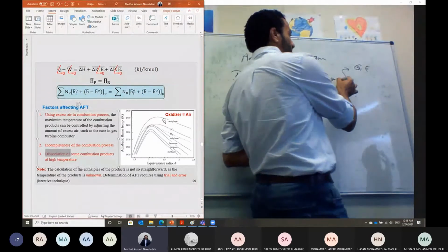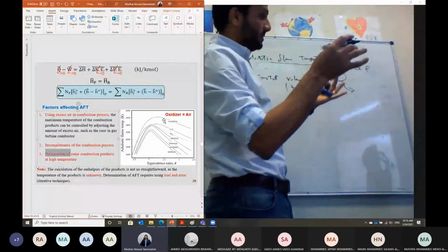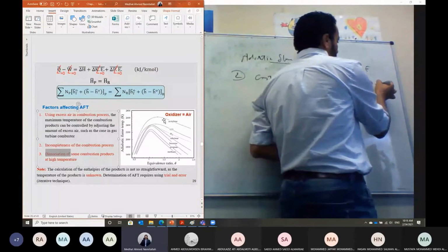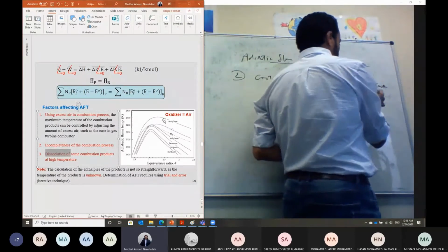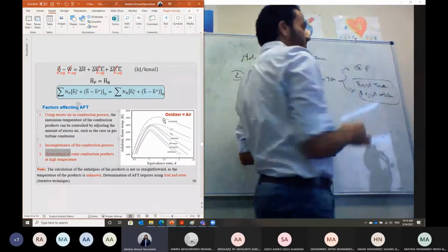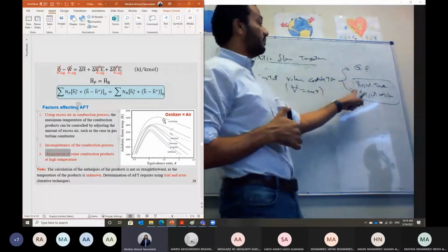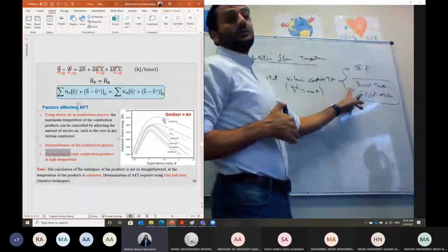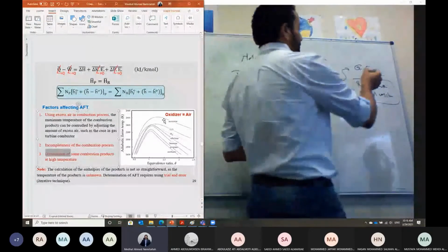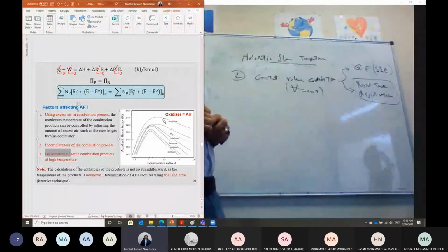And also, guys, if we have an explosion in a fuel tank or something, this is a closed tank. We call it a rigid tank, or a rigid vessel. All of this is a closed system of constant volume. So if I told you I have a rigid tank, rigid volume, closed system of constant volume, or a gasoline or spark ignition engine, that means the combustion is under constant volume.